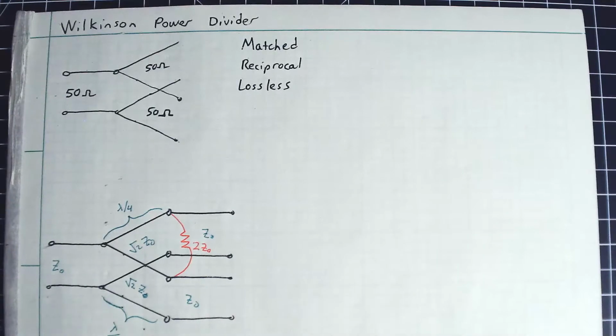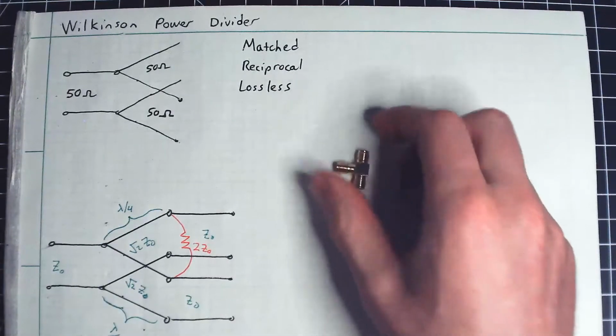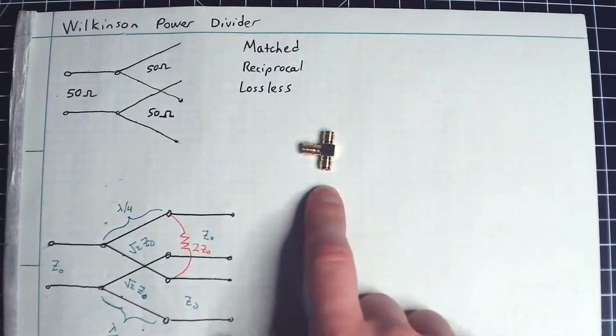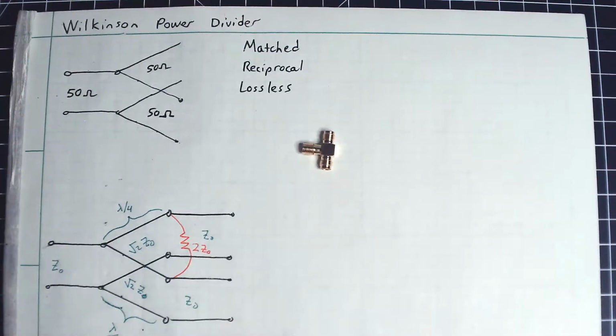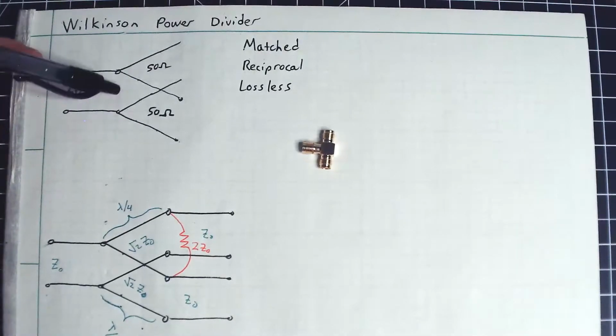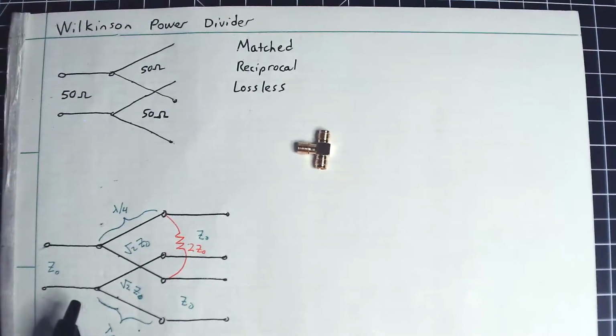There are just many situations where I need some sort of input signal to be branched off into two separate signals. So one very simple device for that is the good old T section. And we talked a little bit about this earlier. Now, a problem that we emphasized in this class is how the T section is not really ideal because it's mismatched. So you do a simple model here where I have a 50 ohm line feeding a branch to two other 50 ohm lines.